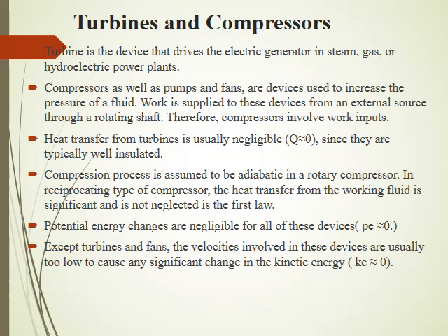The fluid passes first through a set of nozzles, or fixed blades, and here it expands the fluid to a low pressure and high velocity, meaning the pressure energy is converted into kinetic energy. So at the end of the fixed blades or set of nozzles, we have fluid with high kinetic energy.